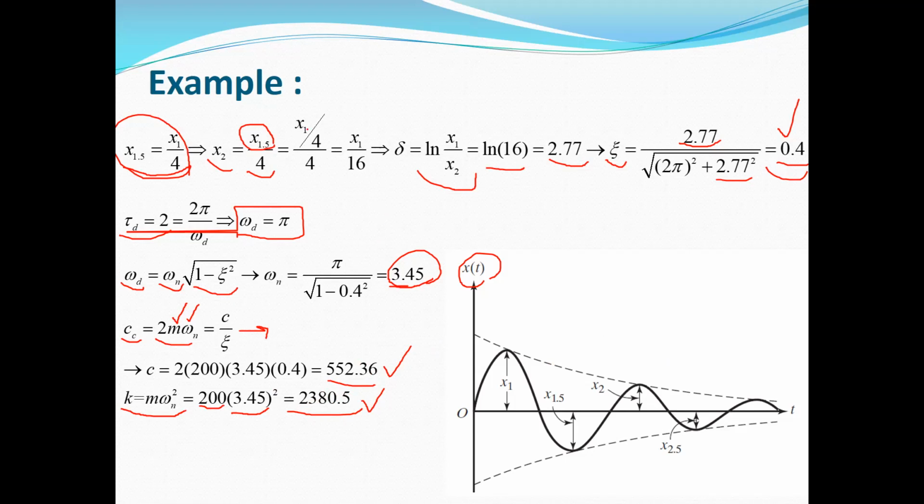Any question? Is it clear? You can see the application of delta, the logarithmic decrement, here. I mean, we have the response. For example, in your system, you have an ideal response and you want to achieve this ideal response. According to this response, you can design your vibrating system and obtain the stiffness, the damping constant, and sometimes even the mass in your system. I mean, you can add, for example, additional mass to control your system. Is it clear? Any question from this example?